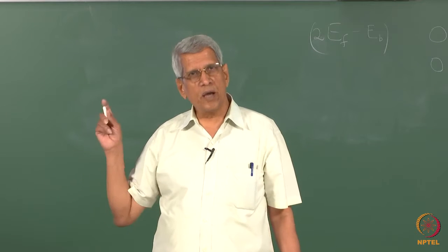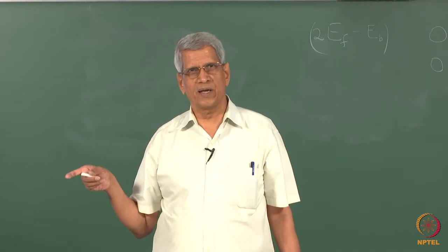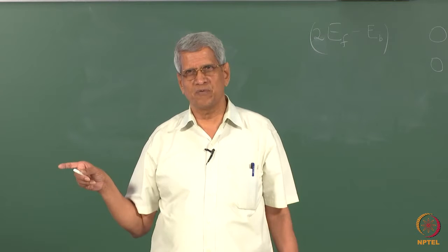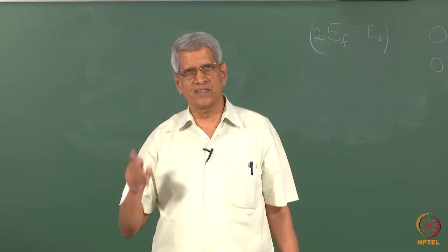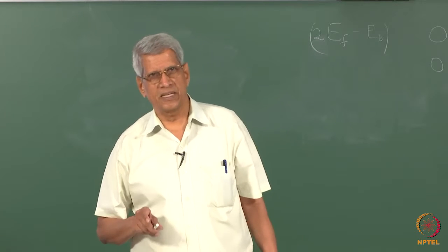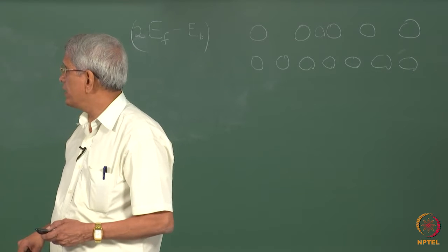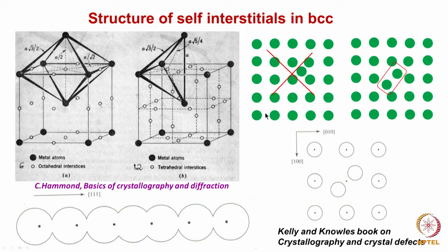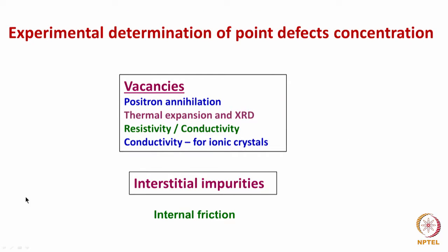That is what you can make out, that compared to vacancies, there are many types of configurations in which the interstitials can exist in crystalline materials. Here what I had shown is that though this is the simple configuration which we considered initially, the final configuration which actually has been seen in real systems is of this type, not what we earlier started with as the defect configuration.